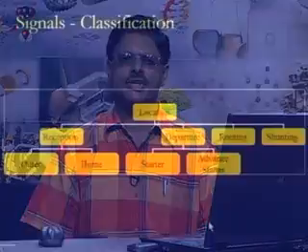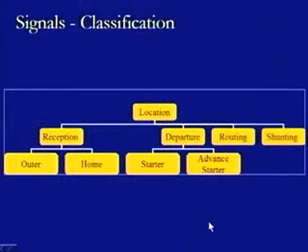These signals on the basis of the locational characteristics can be defined as shown in this chart. The locational characteristic defines them as reception signals, departure signals, routing signals, and shunting signals. Within the reception and departure signals, they are further classified as outer signals or home signals, and starter signals or advanced starter signals in the case of departure.